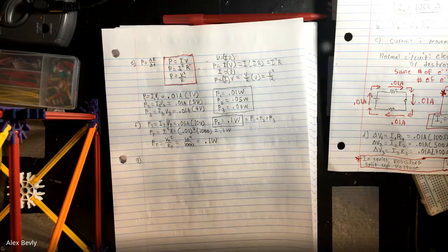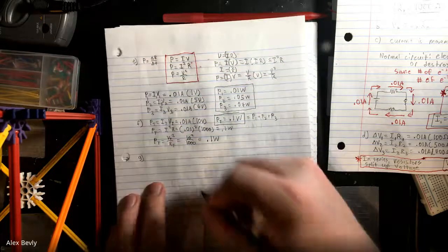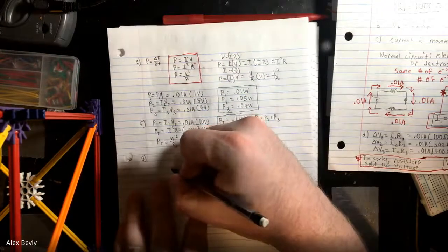So now this is kind of a point where we talk about the difference between voltage and voltage drop. I can have an absolute voltage at a point, say I have 10 volts of potential at one point, or 5 volts of potential at one point. Or I could have a voltage drop. I could say the voltage goes down by 4 volts across a resistor, or the voltage goes up by 10 volts when I go across a battery. So let's draw this out one more time.